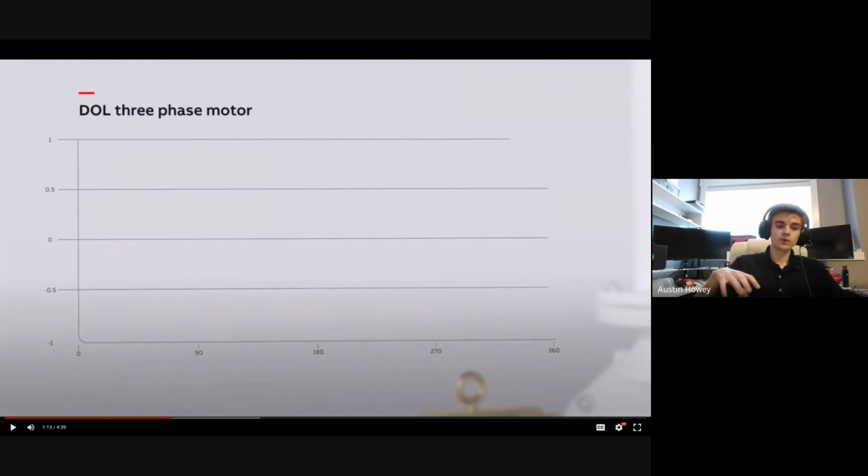Okay, so before they showed that there was a problem with older motors, and then the solution was optimizing for a variable frequency drive because it saves you 40 to 60% energy. So that is the foundation point. But it sounds really good on paper. If you look at the obstacles and the different variables that come with a VFD, there are tons. You can actually run into more problems than you would not running one, because of the way that the energy is fed through the line. So you have to be very careful.